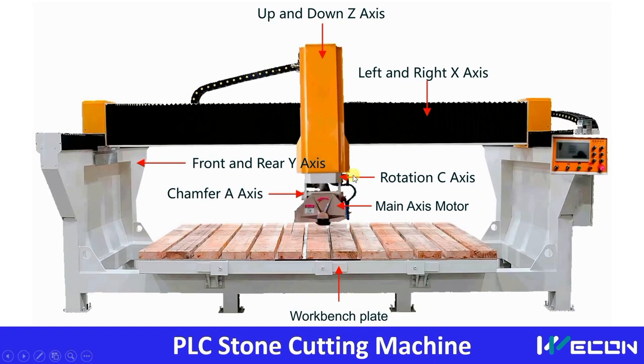So first of all, in any CNC machine, there are three main axes which are called X, Y and Z. So here you can see this cylinder. Here there is the movement for the Z axis which moves this cutting wheel or cutting motor grinder in up and down position. So here you can see up and down, the Z axis. Now this is the whole tray. In this tray, this assembly can move towards the right or towards the left. So this axis is denoted as the X axis.